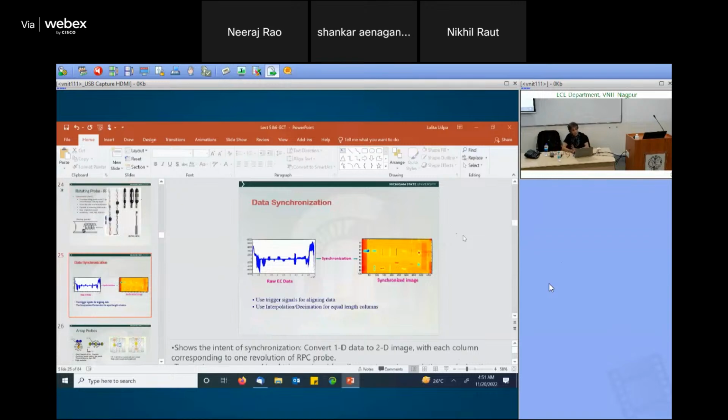If you use low frequencies, it can also go to different depths. But see, ultimately, wherever the defect is, at whichever depth, you are only measuring the surface field. But at low frequencies, this surface field will have information about deeper defects. At high frequency, it will have only surface information. The field is on the surface, but the information could be deeper.